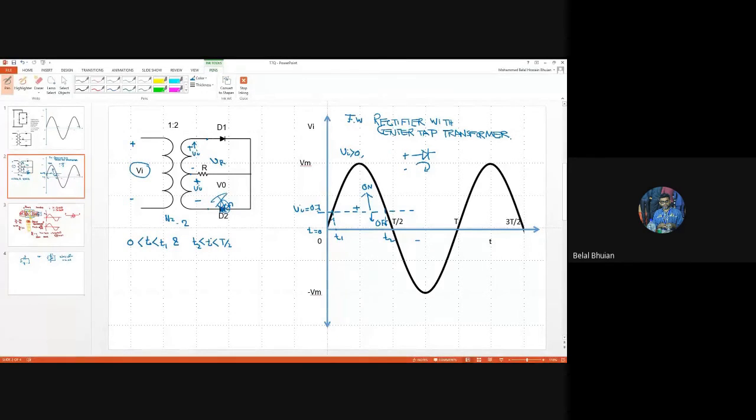You see, we are below the dotted line, so the diode is off. So that means Vi is less than 0.7, the diode is off. On the other hand, t is greater than T1 and less than T2. All the values of the signal are above the dotted line.